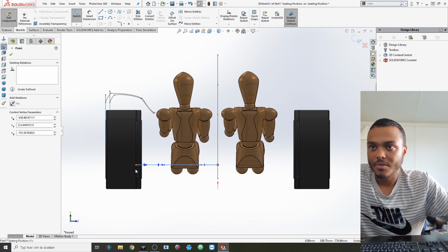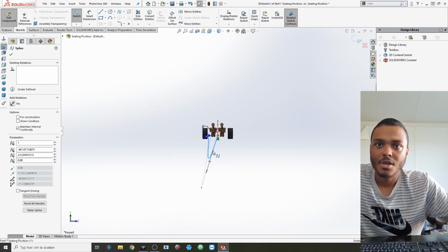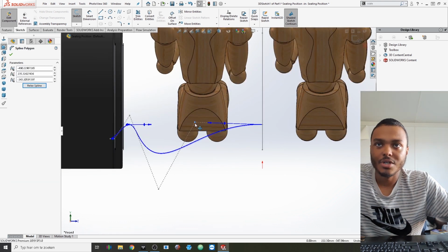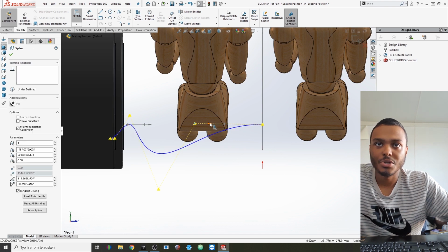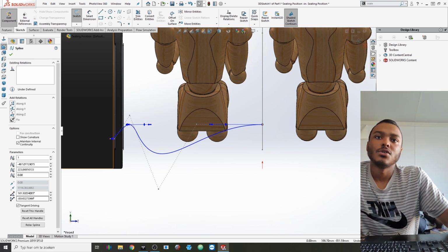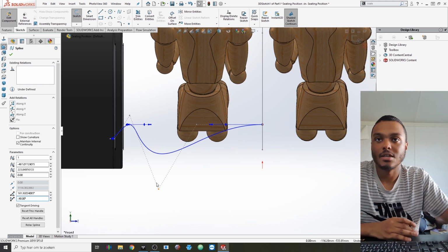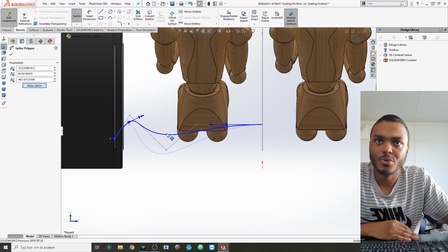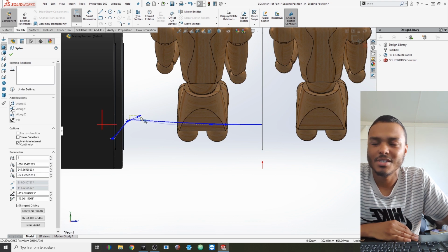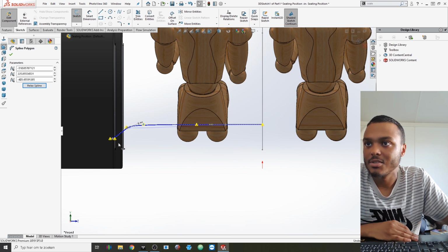I'm going to drag this line a little bit downward, and you can see it going all over the place, but that's not too big of a worry. So we're just going to take this line and pull it forward again, and then take this point here and use this line, where you see -90, which means it is now perfectly flat, and if you mirror it to the other side there wouldn't be a crease or anything. That is what we want, and all of the points that go towards the center require that, because otherwise you would see folding lines or indentations when you mirror it to the other side. So that is a way to keep your body surface clean too.